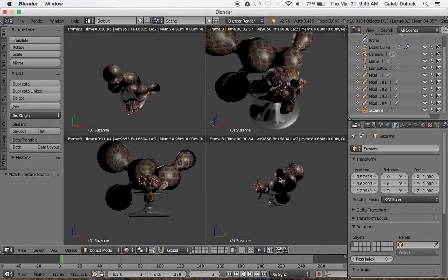So if your lighting's in the right position and your models are placed accordingly, look in each viewport to check that. Always check in quad view. I don't recommend looking at a model in just one viewport. The user perspective is the typical one. It's always good to look in the viewports that show you a straight-on perspective or orthographic perspective without any distortion from the viewing area. So you look over your model and make sure that everything is positioned correctly, lights look good, and all.